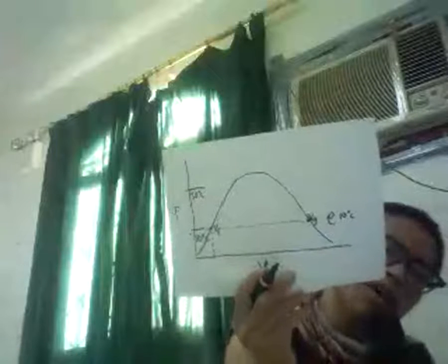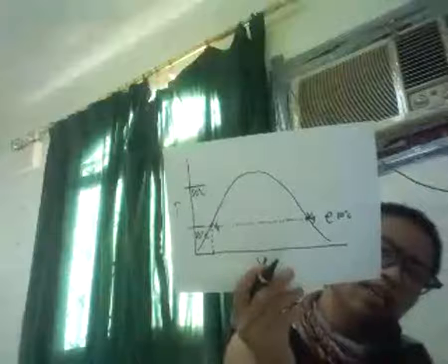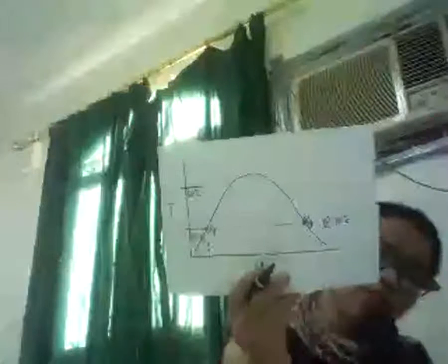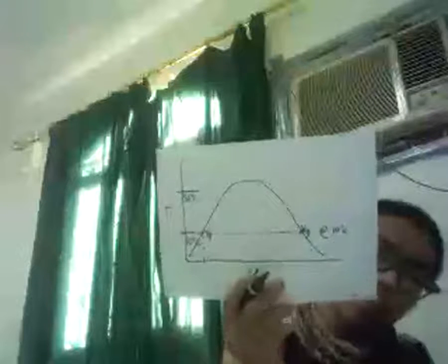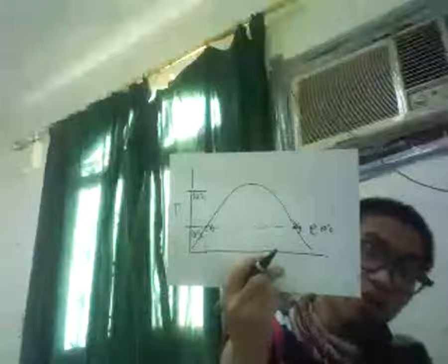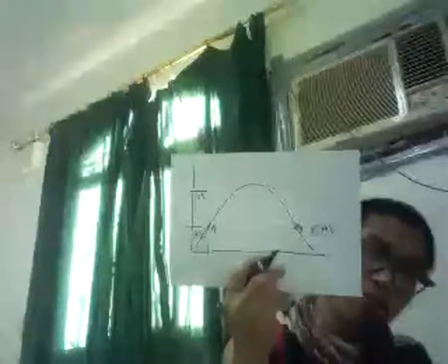At Vf, this is known as saturated liquid. Okay, saturated refrigerant 134a liquid. And then at the Vg, it will vaporize and become saturated refrigerant 134a vapor. It's no longer steam because we have another substance or component being considered here. Okay, now let's go to the 50 degrees Celsius.